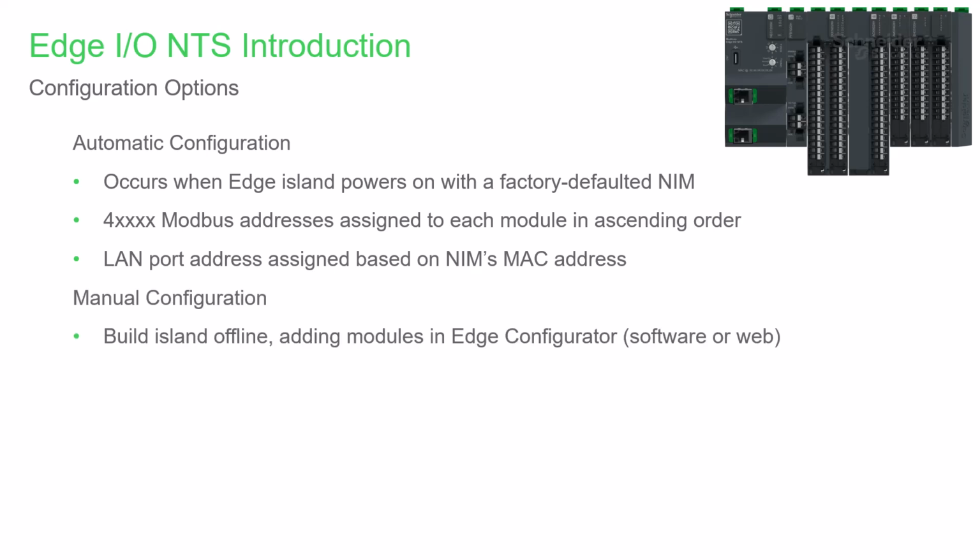However, it's likely that you'll want to do at least some manual configuration of your Edge I/O island. The Edge Configurator software tool or the NIM's built-in web server may be used to configure the island. There are 2 ways you can do this. You can create an island offline by adding modules in the Edge Configurator, then downloading that configuration to the NIM. Or you can physically assemble the modules as required, then perform a scan and create configuration to generate a file